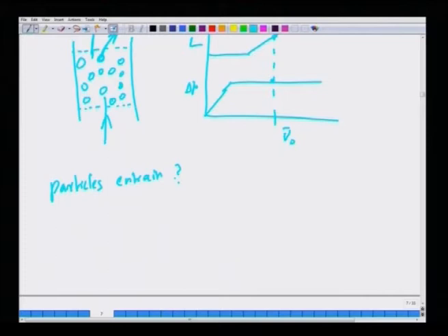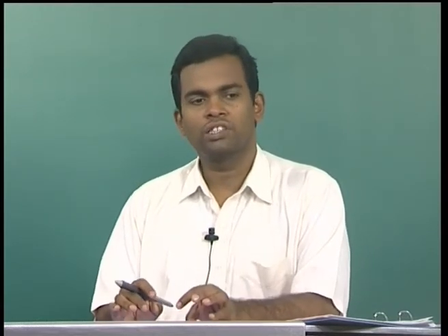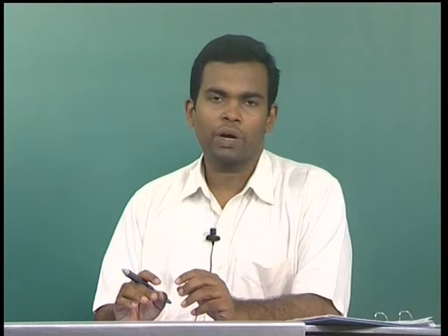Well, the answer is very simple. Imagine that the fluid velocity is slightly above the fluidization velocity. There will be a drag force acting on the particle which will tend to push it in that direction. Now, let us not assume that the particles are in touch, because they are already fluidized. They are somewhat independent, although they will be colliding once in a while. So, we can roughly estimate whether the particle is going to stay inside the bed or go out by just comparing the fluidization velocity with the terminal velocity of the particle.